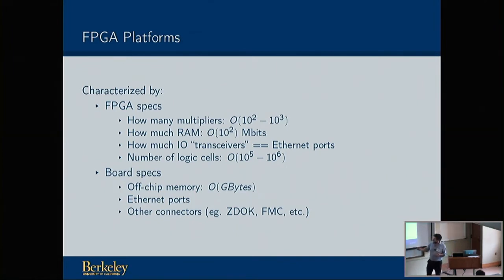And also a slightly more hand-wavy concept: the number of logic cells. The actual number of logic cells is very easy to define, but how many you need for a given task is perhaps a little bit more tricky. But in any case, in modern FPGAs we're looking at millions of logic cells. The logic cells are where you do very general purpose signal processing, so any of your if statements, multiplexers, anything which can't be expressed as an arithmetic operation or a memory block.